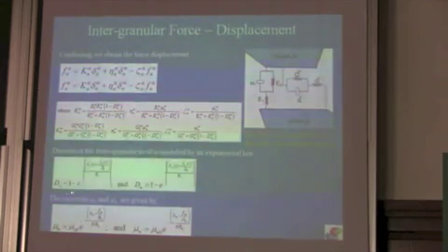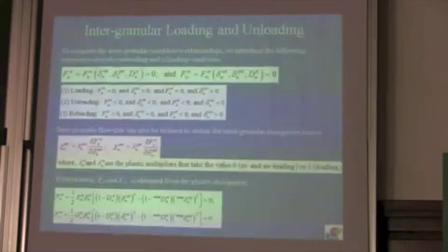The damage function in this case we assume to be of exponential type, so this is the damage function, and also we assume the viscosities to have an exponential decrement with the loading. Now this is not necessary, but the experimental results are best modeled with this additional assumption.